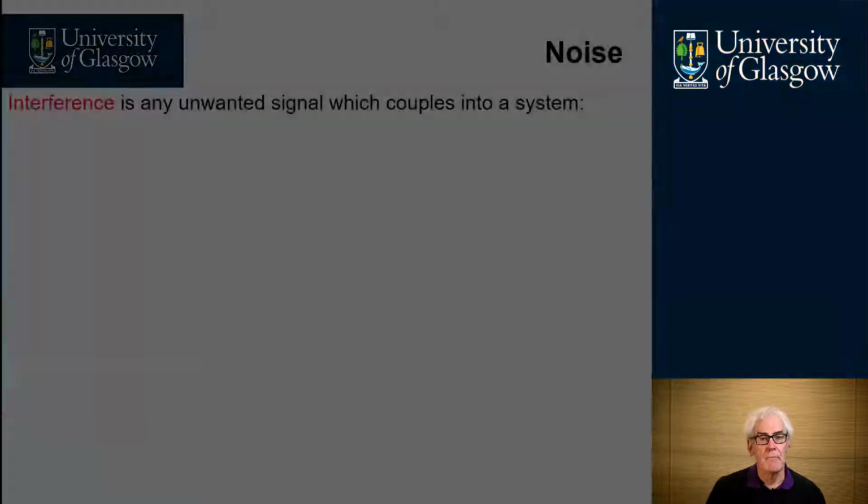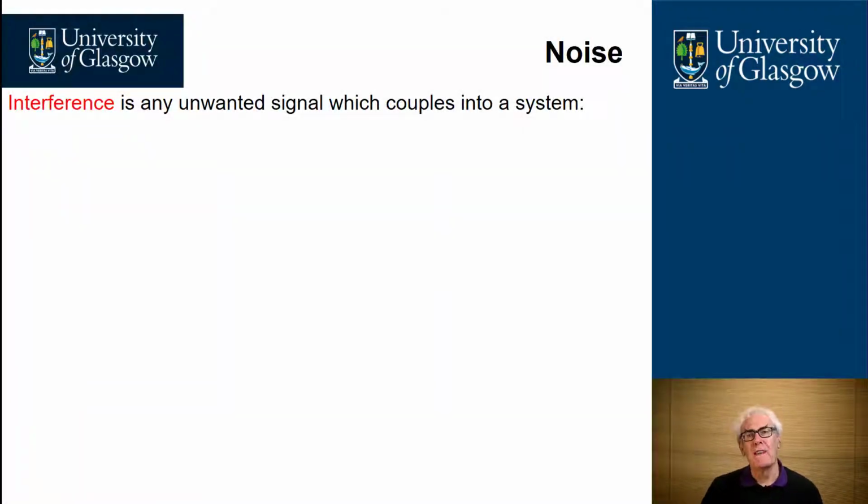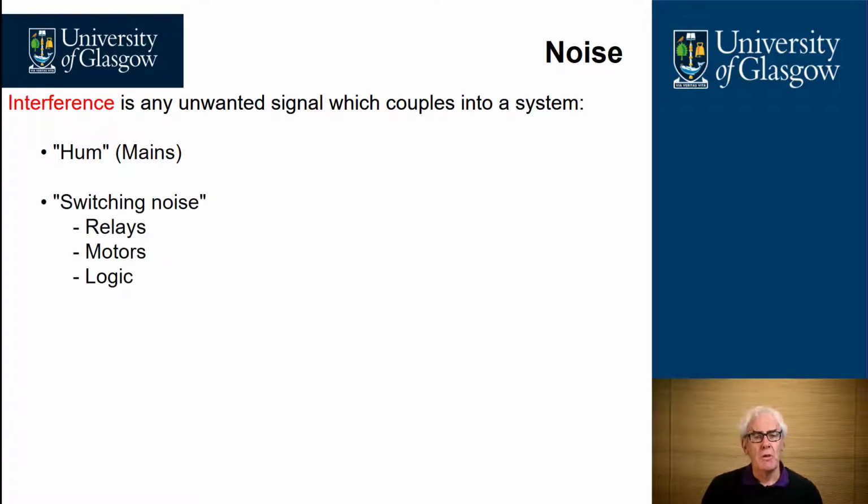First thing I want to do is talk about the definition of noise. Many people mistake interference with noise. Interference is any unwanted signal which couples into your system. It could be mains hum. It could be switching noise from perhaps large motors or relays or logic switching.